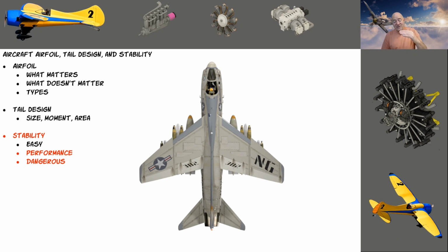The reason they do that is you have a huge amount of moment there. On the full-scale aircraft, the reason they have that is if the plane happens to go supersonic by accident, or it's intended to go supersonic, the stabilizer still has control of the pitch. Planes with an elevator that goes supersonic, the shock wave, I'm not going to get too nerdy, basically makes the elevator ineffective. But a stabilizer stays effective.